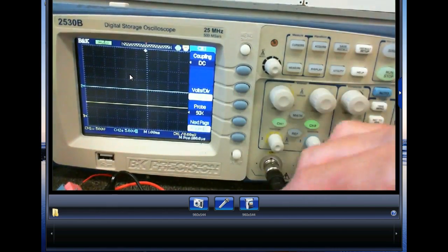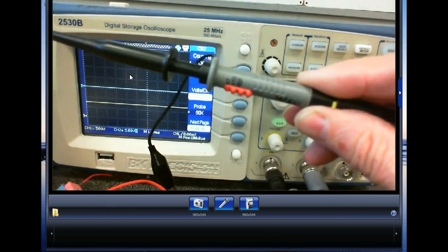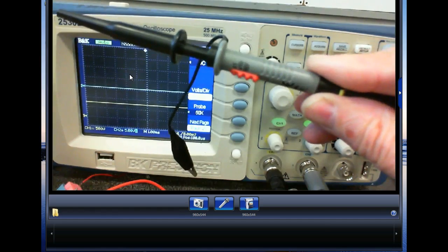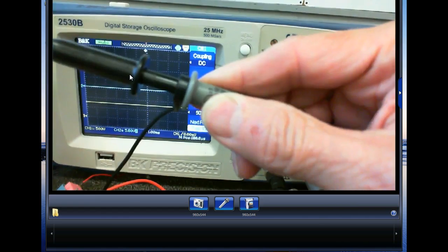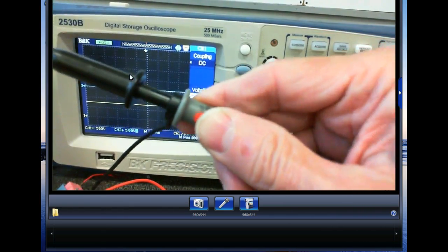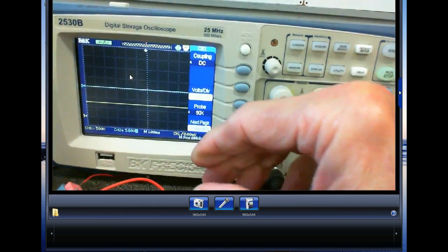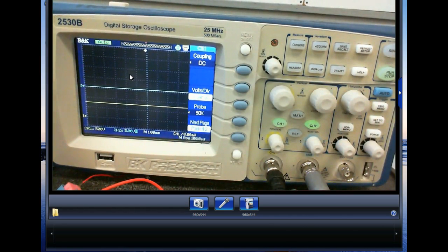Now most of your probes now, a times 10 is so popular that it comes with a switch on the side of it where you can change it from what? From times 1 to times 10. Yeah, it's called reference on this probe. This is the first probe I've ever seen. The problem we have is what is zero? So what we have the ability to do here is we can switch the tip over to ground, so we'll actually see where zero is at.